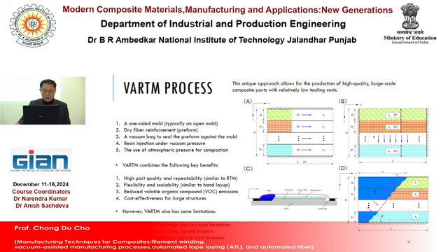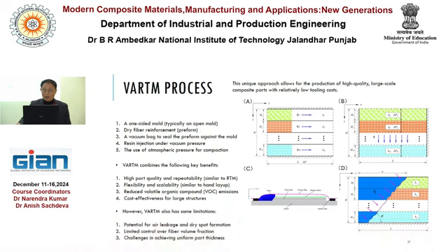Another one is RTM. So both techniques were combined into one. That is VARTM. VARTM process means one-sided mold. There is no upper mold. Only lower mold is needed. That is open mold.